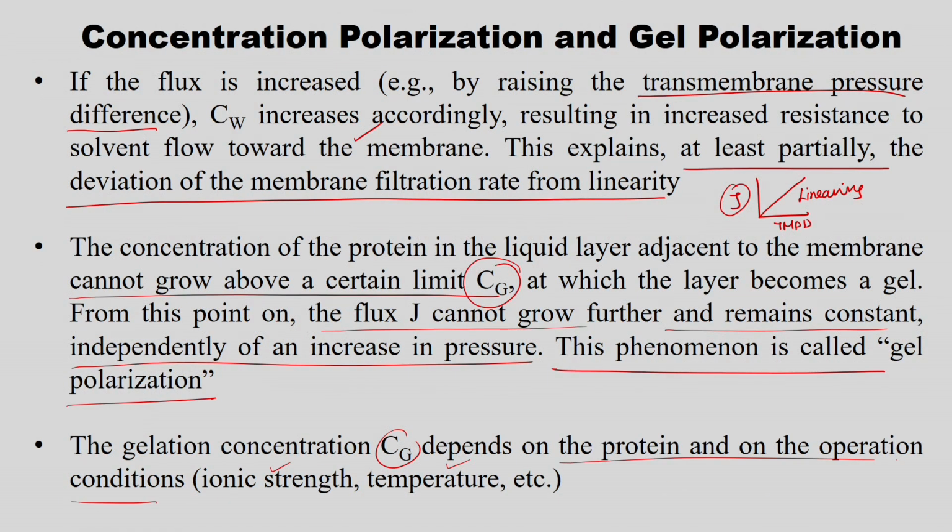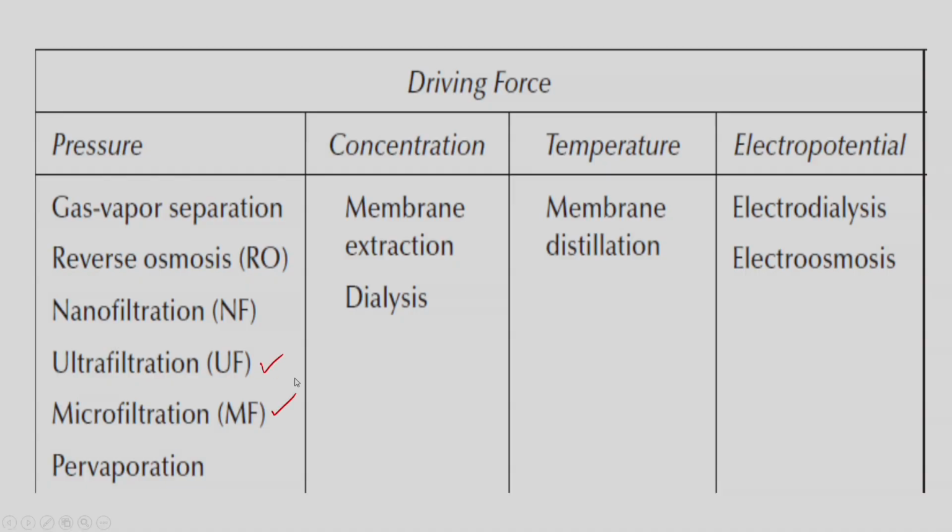So, these were a few things we needed to know before going to see the different membrane processes. Today's lecture we will probably cover two, which are microfiltration as well as ultrafiltration. So, here are the driving forces for different membrane processes. Based on pressure we have all four varieties that we concentrate on, particularly in food processing. Pervaporation and gas separation also come under the pressure driven category. The concentration driven ones are membrane extraction as well as dialysis, and membrane distillation is a temperature driven process.